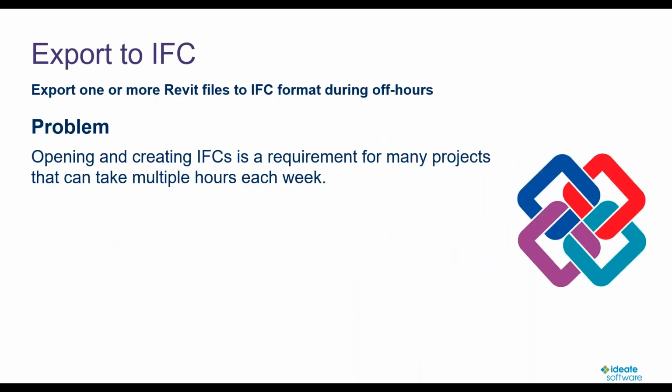So let's look in more depth at exporting these IFCs. The main problem with exporting IFCs is you have to manually open the projects and create IFCs for many projects. It might be one project, it might be 10 projects. If you're looking to do these weekly or daily or whatever, this can take a lot of time and a lot of hours to produce these files.